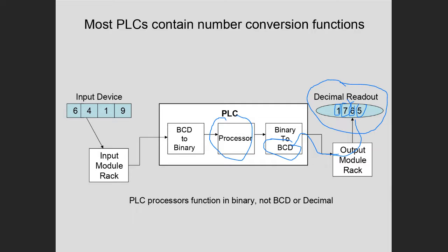So binary coded decimal, BCD, is normally used when you want to input separate digits of a decimal number, or output separate digits of a decimal number. When you're outputting separate digits, typically you're going to use something called an LED 7-segment display, or there's LCD, which is liquid crystal display, but even the LCD is 7 segments.